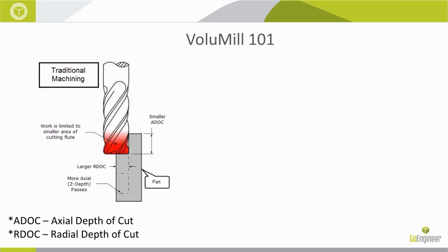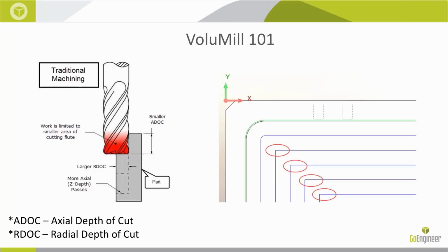That will indicate how much material is being removed. With this type of operation, it could be anything from a pocket in or a pocket out routine, but you're going to be focused on your depth of cuts and how much you can take, and as far as your chip load there.